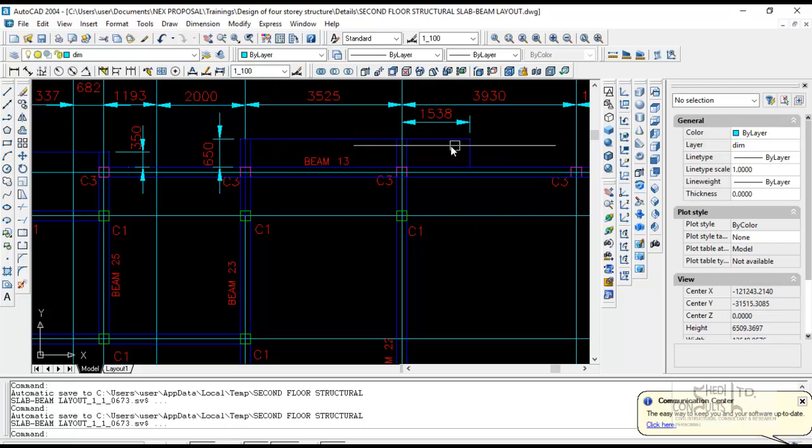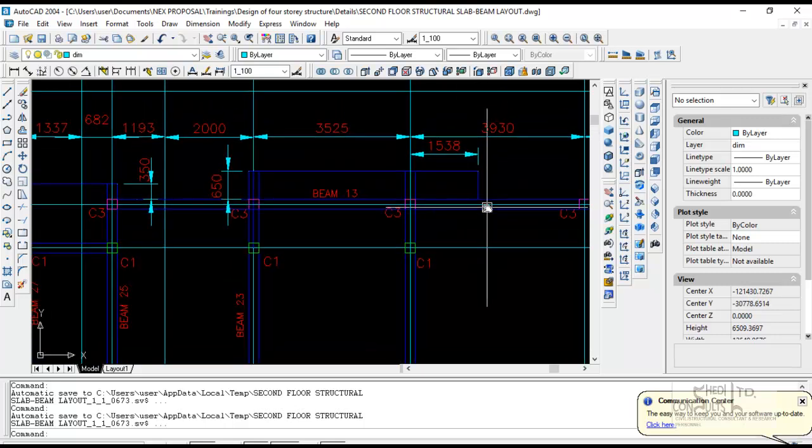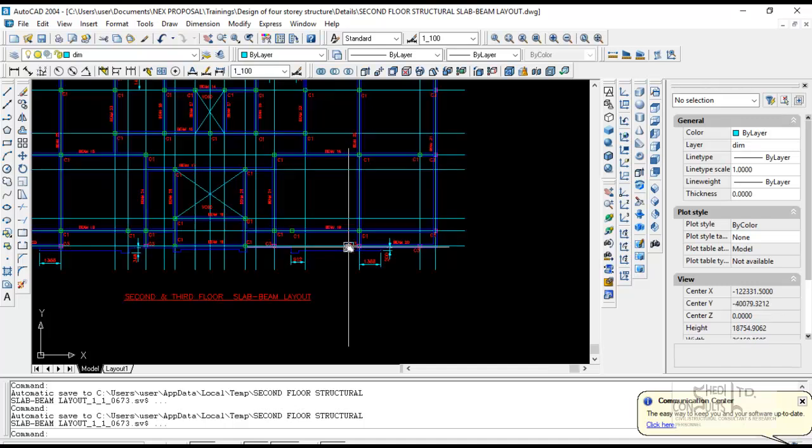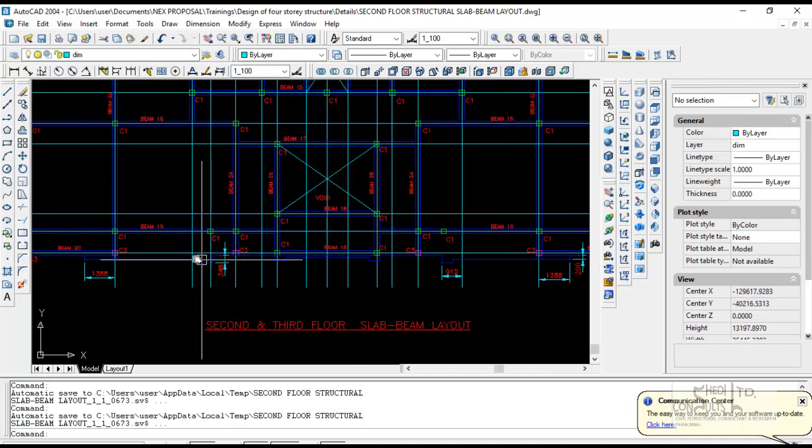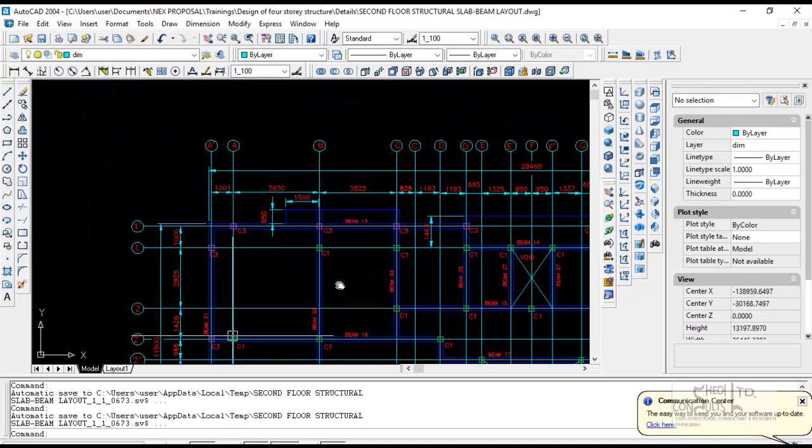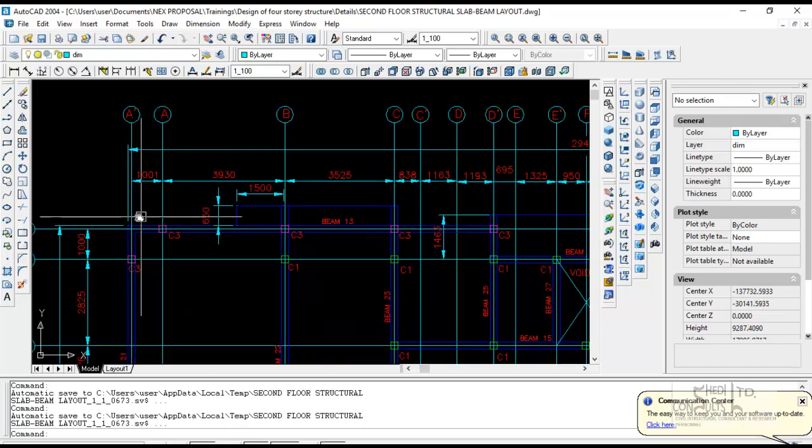So the load from this small cantilever is just the total loading on the slab times the overall length of the cantilever, which is this width. So you may choose to also calculate the loading associated with these small cantilevers. They are negligible anyway, but you may choose, if you have significant cantilevers all around the structure, the dead load.